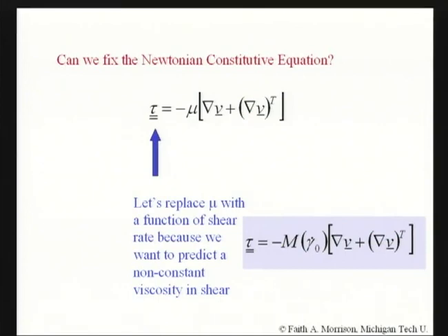But the bottom line is that this is a parameter of the model, and it's only later that we determine that, oh, look, when you put steady shear flow kinematics on it, whatever is out in front of gamma dot turns out to be the prediction for viscosity. And after noticing that, we say, why don't we just call that parameter the viscosity? In other flows, there will be other material functions that will have this parameter in them, and those material functions won't be called viscosity.